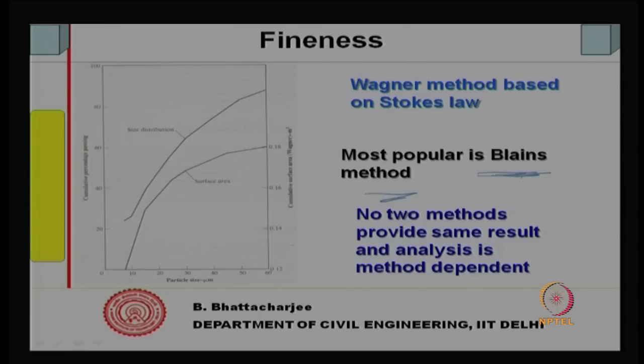But before that, it is important to mention that no two methods provide the same result, and the analysis is method dependent. Like time of transition, as I said, whatever particle size distribution it gives, laser diffraction does not give the same thing. Neither will the hydrometer analysis give you the same thing. If you do it through microscopy, it won't give the same thing. So every method has its problems, but they can be used for relative comparison.